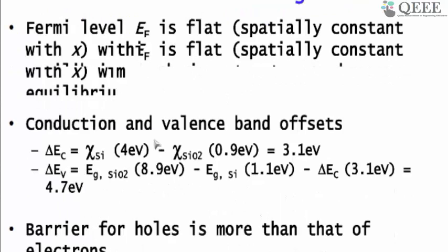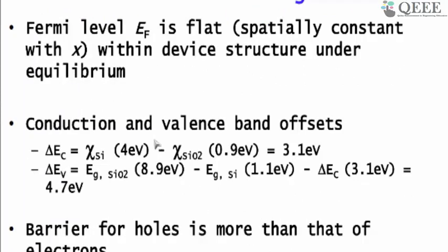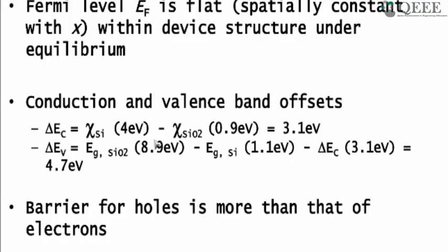Next, these materials are heterogeneous. In a p-n junction, silicon is present on both sides of the junction, but here you go all the way from metal, then insulator, and then semiconductor. Then you need to consider some other parameters, known as electron affinities and work functions.